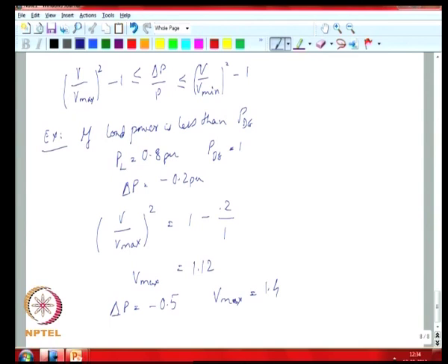Okay. Of course, at a voltage of 1.4 you can damage the DG and other equipment, you do not want the voltage to go that high. So, here we have quite a few assumptions. We are assuming the feeder to be RLC components, and we are assuming that power injection is still happening at a constant rate. So, beyond some critical limits these assumptions may not be valid, but definitely you will see an over voltage.